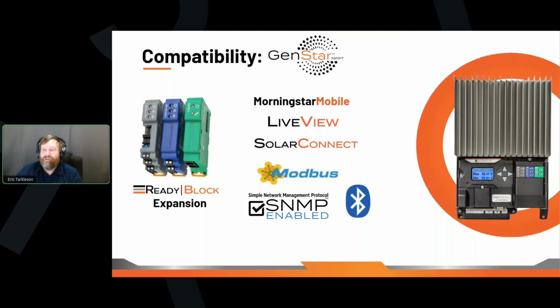It's also worth mentioning that Modbus is served through the Ethernet IP port on the GenStar. So any data that you see in SolarConnect, there is a Modbus address for that you can get at it for other site monitoring, connecting to PLCs, SCADA systems, things like that. And the GenStar and the ReadyEdge also have SNMP enabled. So if you're online, that's another access to get your data off of your local site onto the broader internet. And if I didn't say it already, also Bluetooth. The GenStar has Bluetooth built in, and that's how you use it to connect your app.